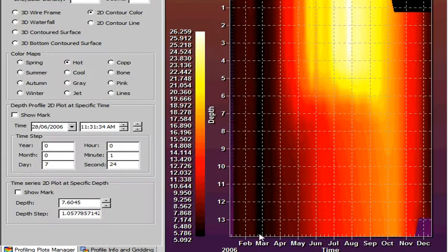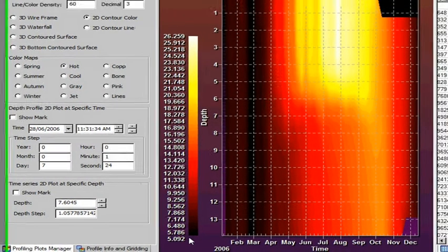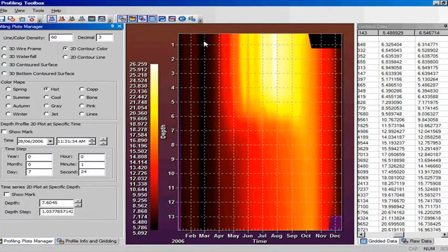As the snow melts, the cold water is coming in, and we can see that's represented by this very dark color down at the bottom, around 5 degrees Celsius water coming in, going all the way through the water column. And then later on in the summer, we're going to get that significant amount of warming at the top, and then later again in the summer towards October, November, anti-stratification, homogenization of the water column towards November and December. So it really allows us to tease out certain elements of our data set.